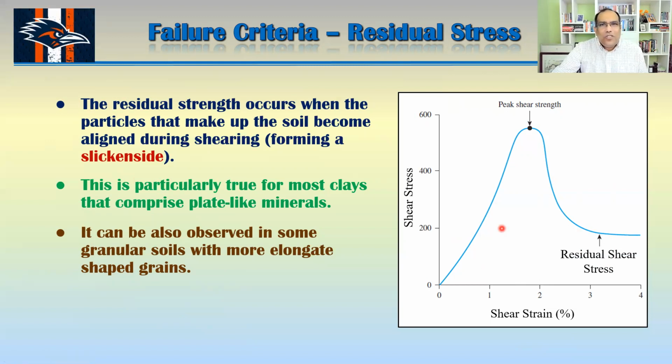In sand, we don't see that kind of phenomenon, but here we can see this kind of phenomenon for clay soil, and this one is called your residual shear strength. So basically this residual shear strength is much lower than your peak shear strength, and your design could be a little over conservative if you use this residual shear stress.